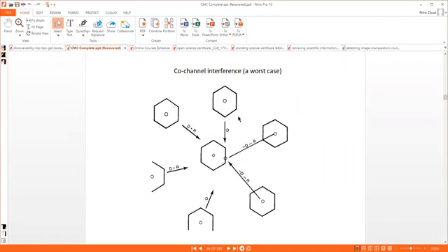Now, in this 7 cells, if we say that this cell site is the one on which the particular mobile unit is available, you can see with this circle here. Now, if we say this circle is considered as the location where the signal is very weak and the interference is at the peak, when we measure the distances from this particular area, we go along with these distance areas. One is D, next one approximately D minus R distance, and one is approximately D plus R. D means distance, plus R its radius of the particular cell site on which we are standing.